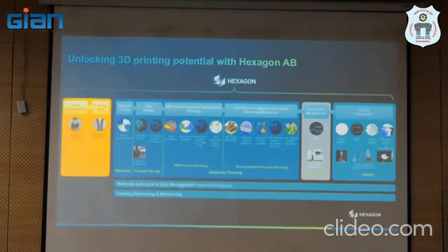While accelerating the car, you will have a different load. While curving, you have a different load. While braking, you have a different load. Like that, there will be 6 scenarios. All have to be passed by the 3D printed component. So we need a better understanding of the loading condition. Once we know that, then we can talk about lightweighting and other stuff. Then we go for performance.